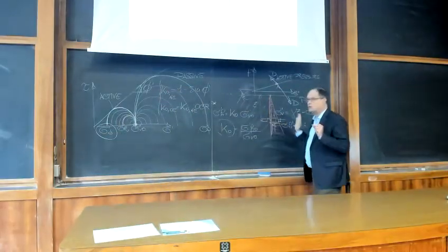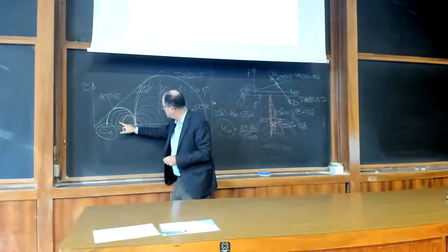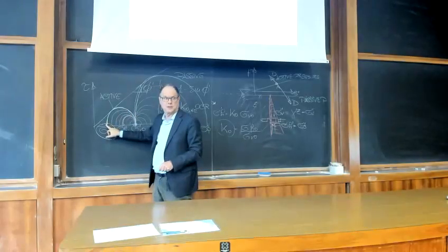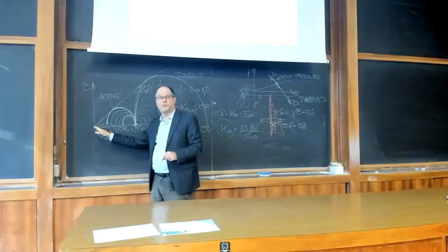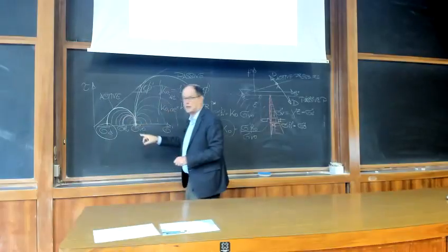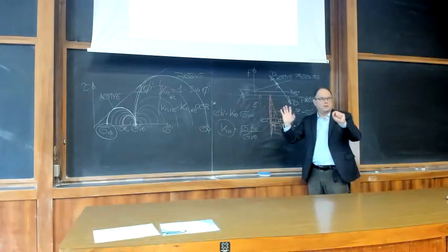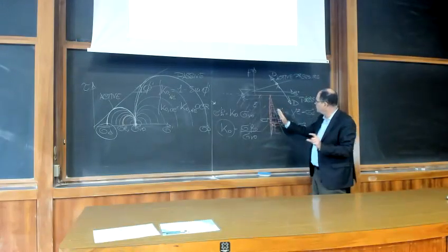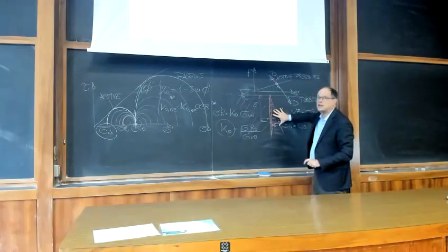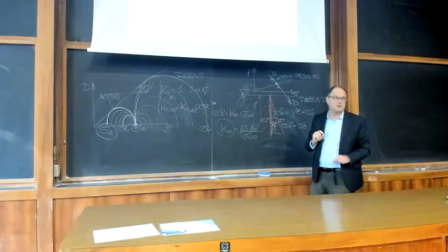So essentially, you move the soil laterally, you reduce the horizontal stress, so you are now increasing the size of your Mohr circle. Once you get to your limit, you cannot reduce further the horizontal stress. So this is the limit stress. And the limit stress is what acts against the wall just before failure. Now, you can still continue moving your wall, but the soil at that stage has failed. And it's failed and will move along these planes.